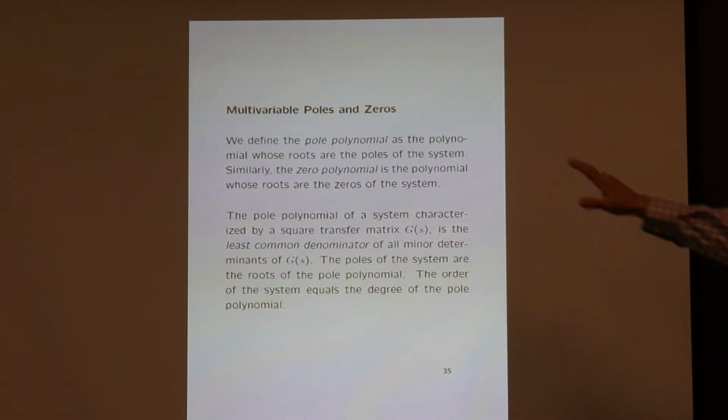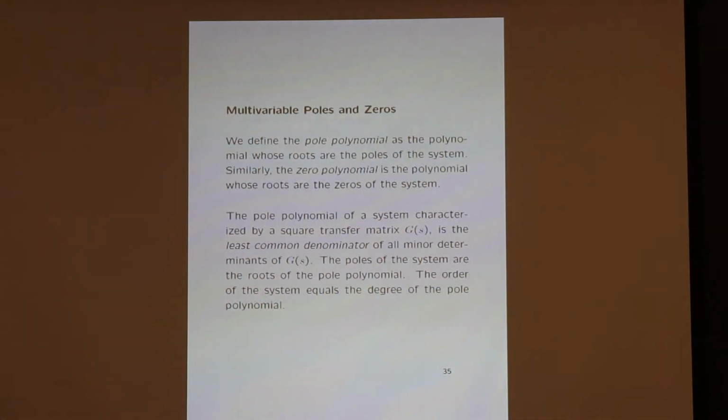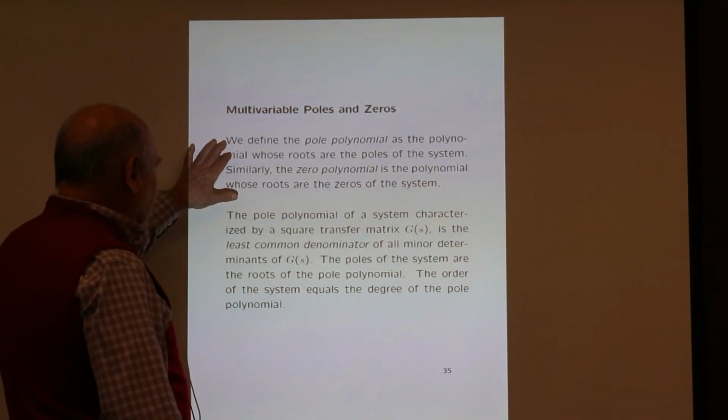Yeah. Well, here it is very important because it allows you to separate non-minimum phase variables from minimum phase variables, and to show that the flat output doesn't have any zero dynamics. So the concept of poles and zeros is very relevant, and especially the concept of zero dynamics. The stability or not of the zero dynamics is important in that particular case. And this has to be done also for discrete time systems.